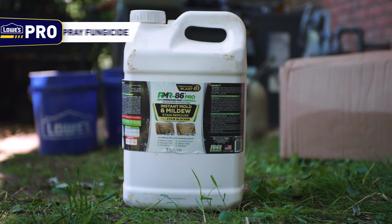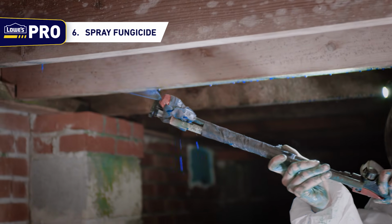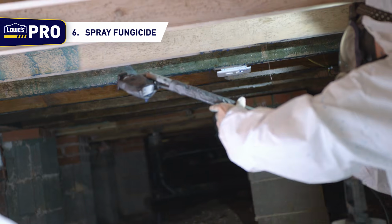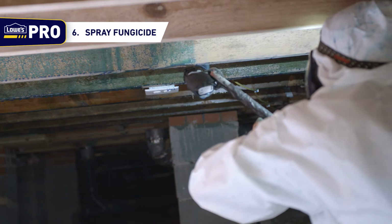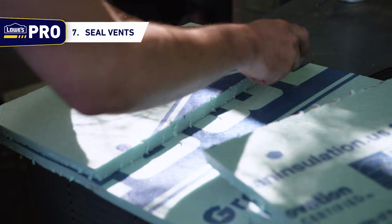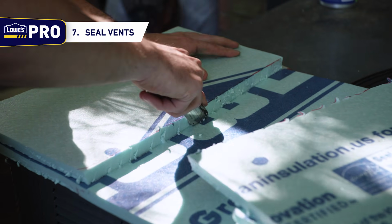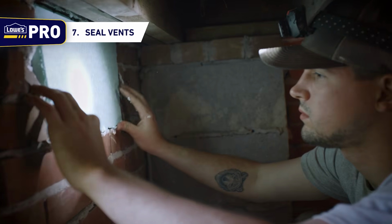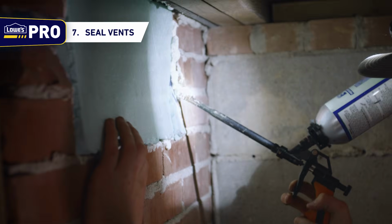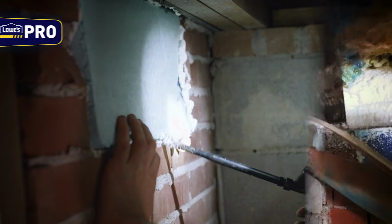Step 6. Spray fungicide. Apply a fungus and mold prevention solution to all exposed wood using a sprayer. Adding a dye to the solution will allow you to make sure that you have even coverage and haven't missed any spots. Step 7. Seal vents. Using 1-inch R5 XPS rigid foam board, measure and cut pieces to fill any vents to the exterior of the house. Once the XPS board has been fit into place covering the vents, use a spray foam to seal around all of the edges.